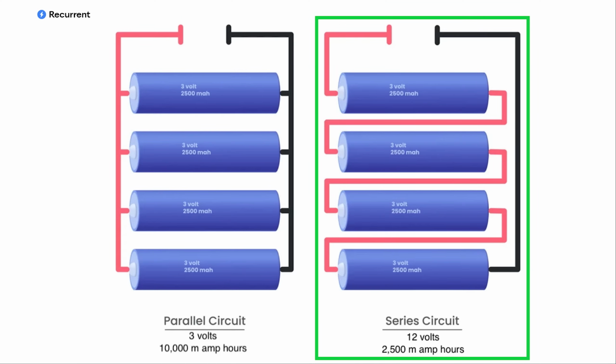But if I've got cells connected in series, then they all have the same current flowing through them, right? And so if one of them reaches the maximum or minimum voltage sooner than the other ones, because we always measure all the voltages on every cell in series, from a safety point of view, we have to do that, I will then stop charging because I don't want to overcharge that one cell that's got to maximum voltage. And then the balancing system would kick in and maybe bypass that cell and charge up all the other ones, which is typically a slow process because we can't put much current through the bypass circuit, if that makes sense.